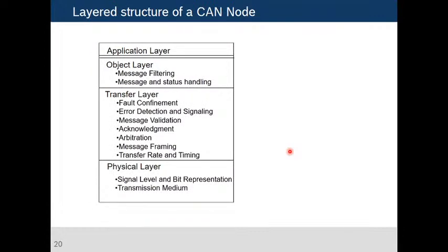We are going to see the details, but the application layer is where we have a complete system, but still we have to see what frames are going on the bus. Then only can we do diagnostics, or during initial development we need to see that. That's the time the application layer is involved on the CAN nodes.